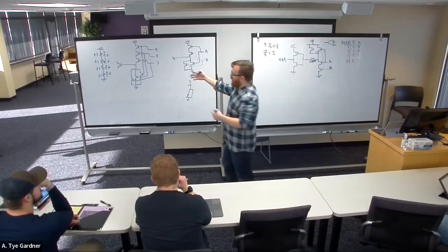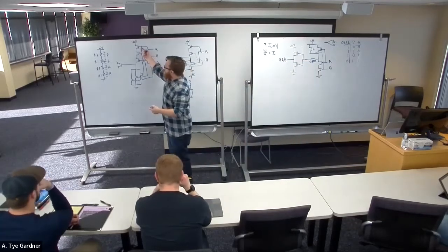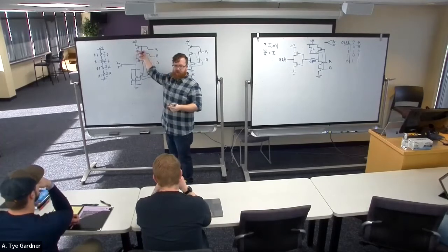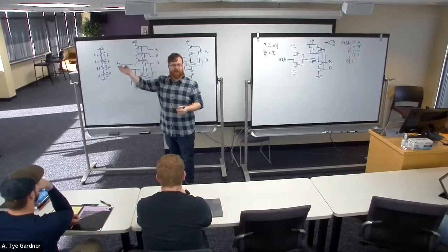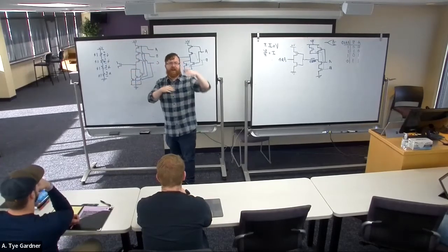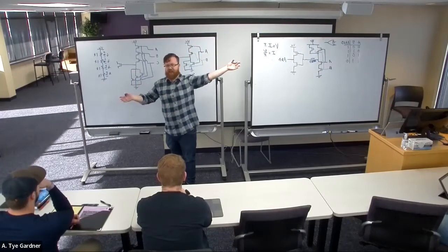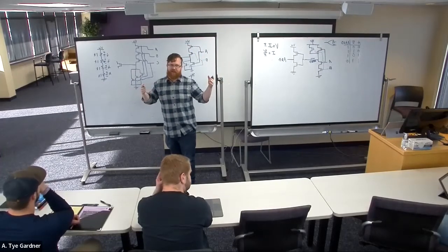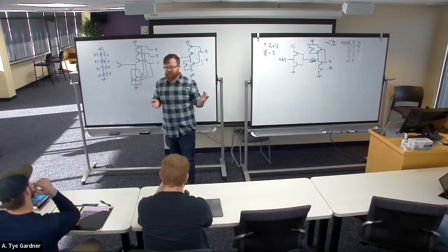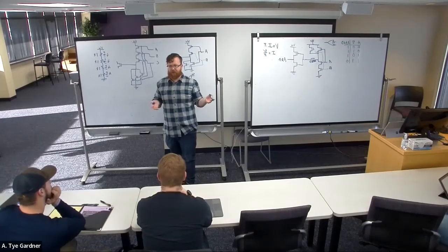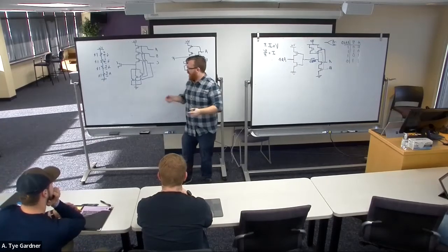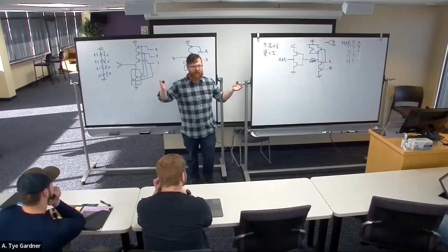I just want to start establishing that from the gate to the other two nodes need a specific amount of voltage. And the higher I pile these up, the less voltage I have available. And eventually I have to stop pretending like they're digital devices and they no longer work. So that's my limit, is what is my voltage overhead, right?